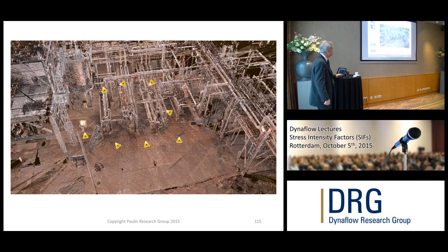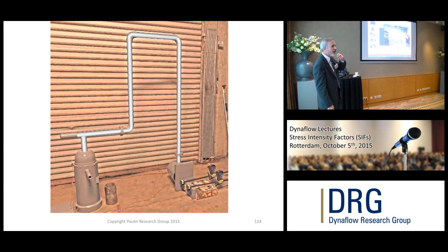We did that with a 2-inch piping system in Houston. It was pouring down rain outside our office. Here was the system, a little system. We just wanted to build something that we could validate the scanner with. It's got a stainless steel cap and a stainless steel cone on it, so we had to run it through FEA Tools to get the flexibilities. We slid a 1-inch block under it, and that was the initial displacement. We wanted to see if the scanner would be able to detect that lateral movement in this length of pipe.